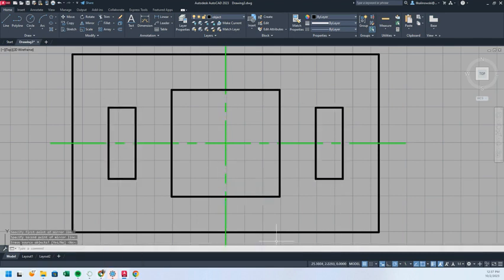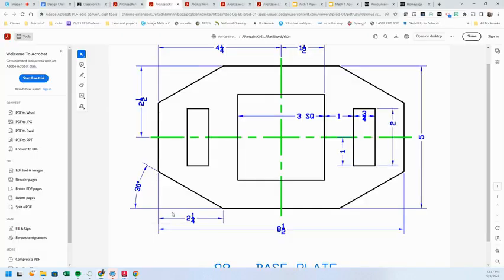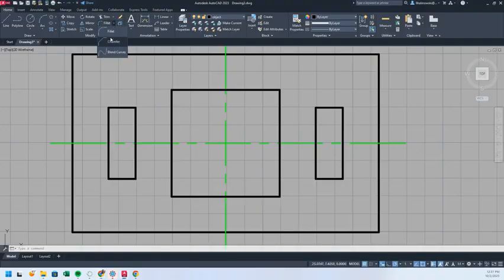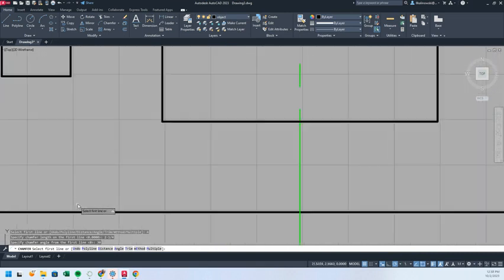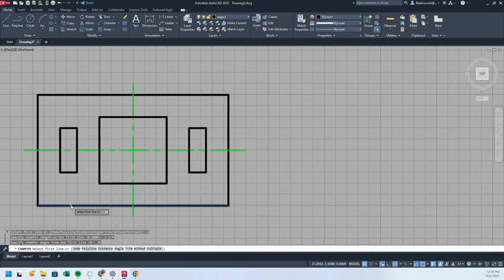And then we have on this one a little corner that we can cut off. So you see right here it says 2 1/4 at a 30-degree angle. I'm going to use my chamfer for that. So under fillet is the chamfer command. And at the bottom, we're going to use angle because we're given an angle. And it wants to know what the first distance is. That's 2 1/4, so 2 minus 1/4. And then the angle is 30. Now, it's important that you choose the long line because that's where the length came off of. So the long line is your first line, and the short line is your second one.